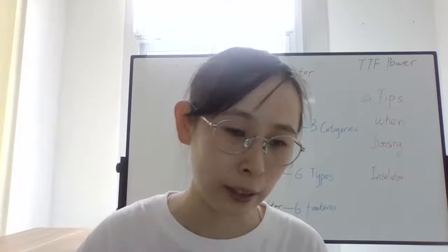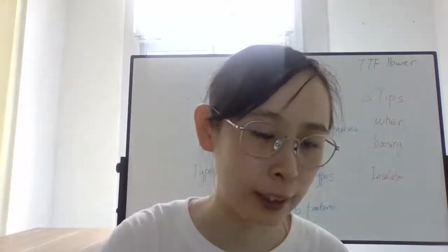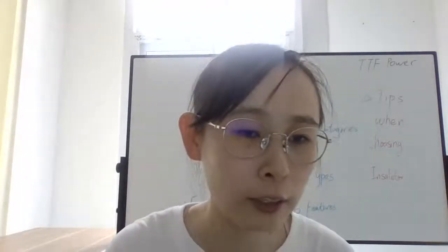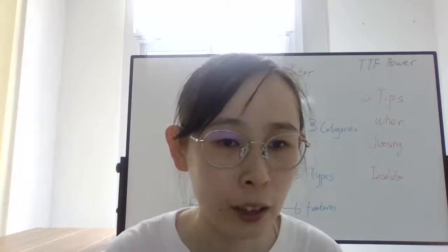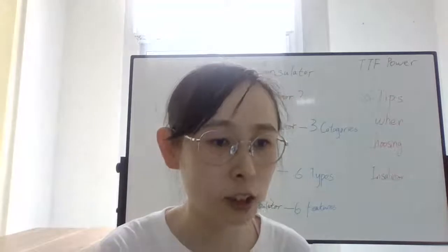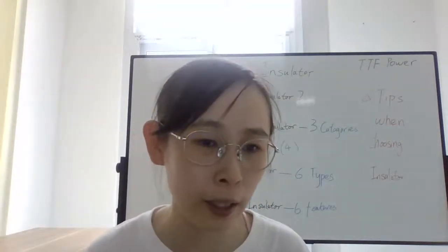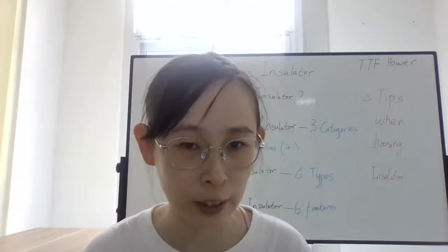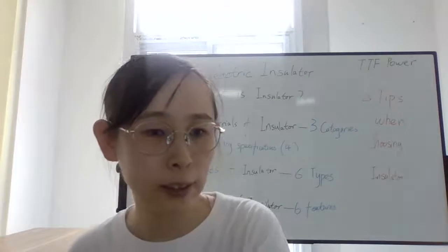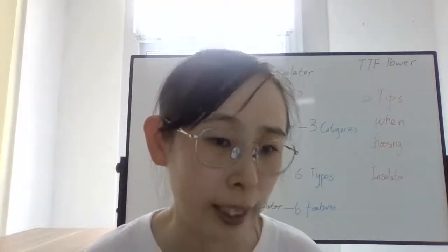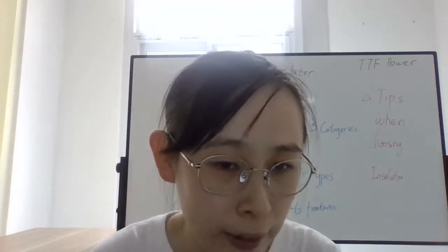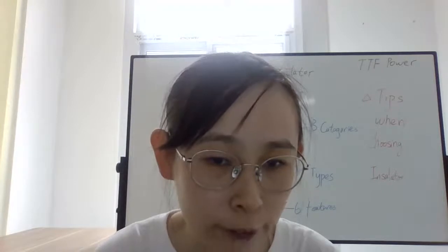Then, the fifth type of insulator is the string insulator. They are also called tension insulators. String insulators are used when the conductor is subjected to high tension while hanging over particular sections, such as areas including sharp curves, river endings, and dead ends. In such areas, there is likely to be a sudden change of direction of the cable.